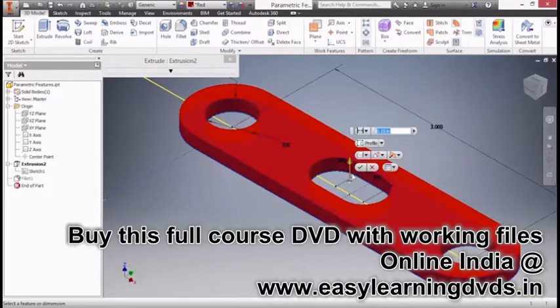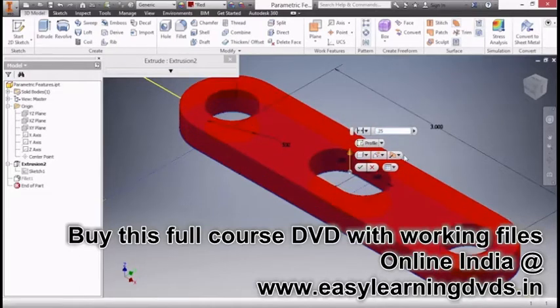So here this is currently 0.15 inches tall, and that's going in the positive Z direction. How can I tell it's a positive Z direction? Well, I can look at this triad in the lower left down here, and I can see the X, Y, and Z Cartesian directions in space. Now I can change these values here, such as currently 0.15 inch to 0.25 inch. You can see a dynamic update happen as you do that, and I'll approve that with the green check mark.